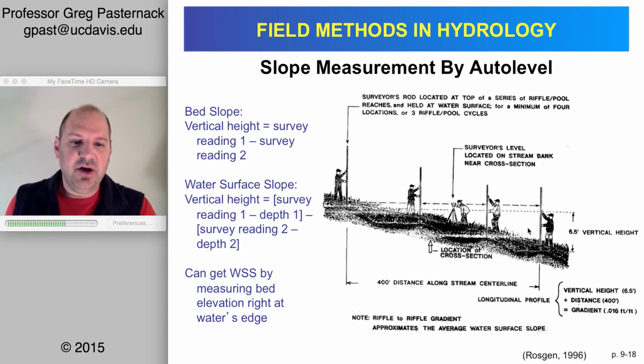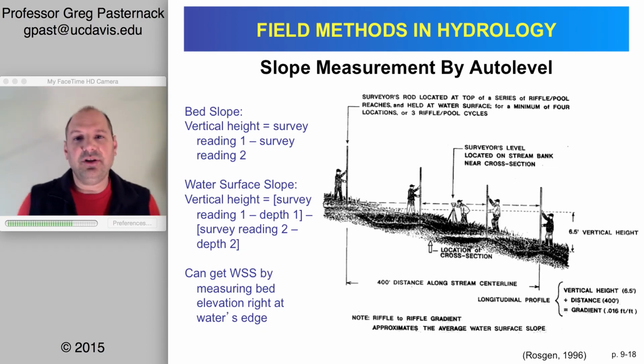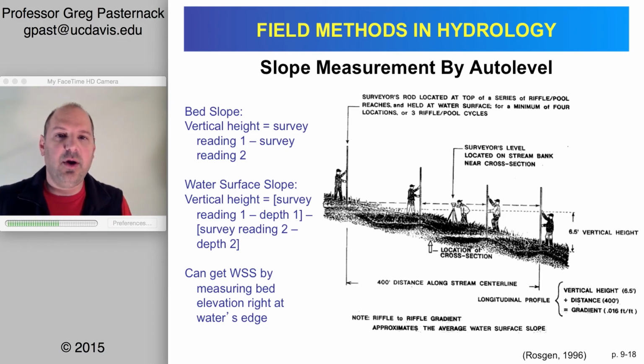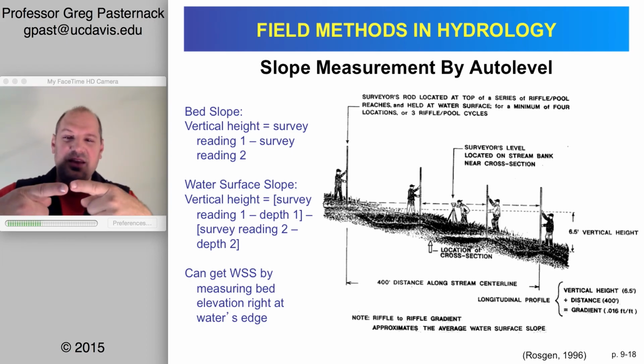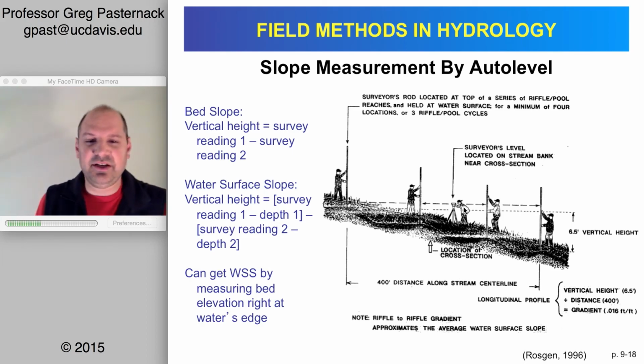Then you need to know the length between those two. That typically means rolling a tape measure out along the length of a river. Or if you're in a straight line, you can use an auto level to measure the distance from where you are to the pole. And then if you can turn 180 degrees and measure the other side, then you can get it if it's a straight line. You know, if you make a turn, no, but if it's in a straight line, you can.